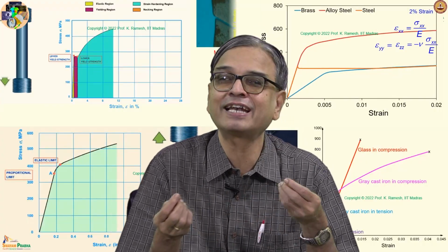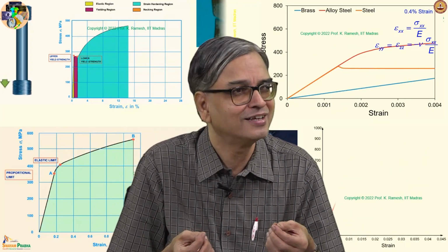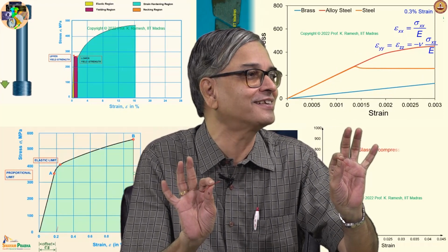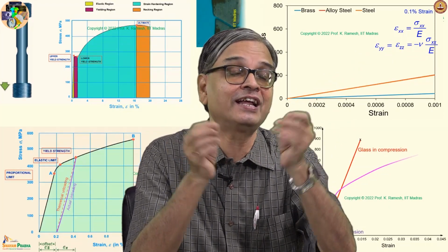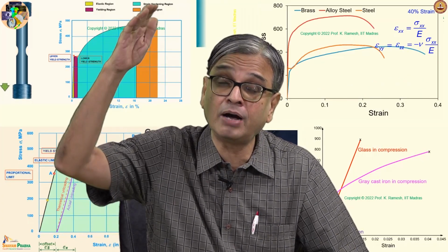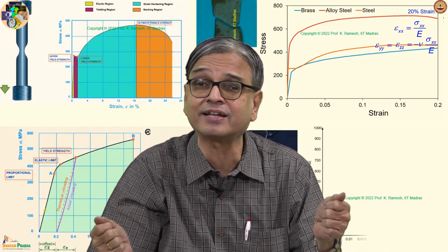So, one observation from this is I need much less load if the loads are repeated. Is the idea clear? And scientists want to relate it to this: suppose we are on the 3rd floor, I ask you to go down and come up once, you will not mind. I ask you to do it 10 times. At the end of 10 times, what will you say? I am fatigued. Will you say that or not? Same thing they have coined for the material. So, when I apply repeated loading, it fails by fatigue, and I will operate at a much lower load than what we have discussed till now about monotonic loading.